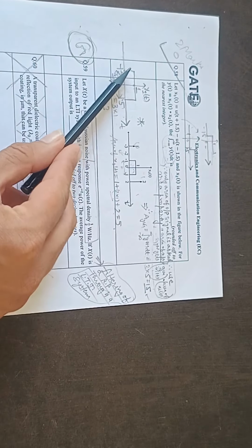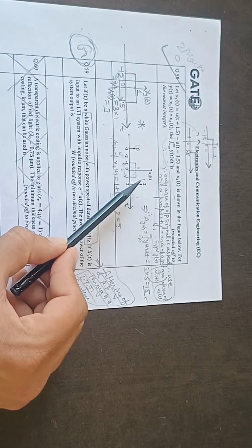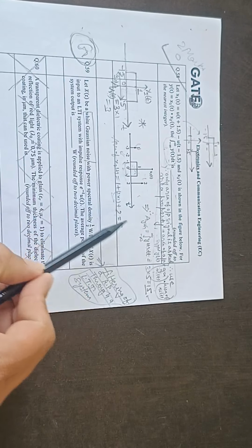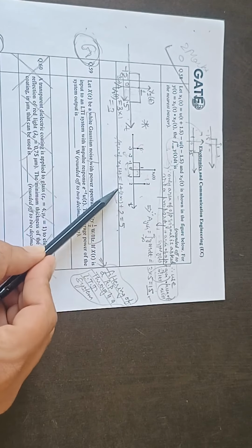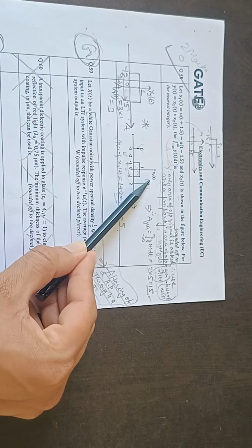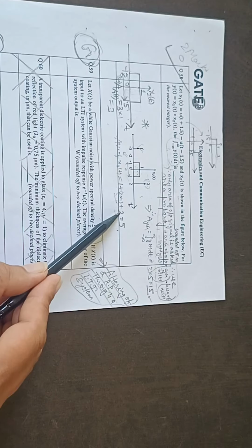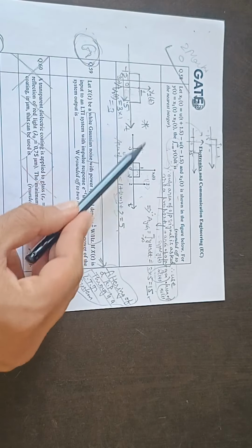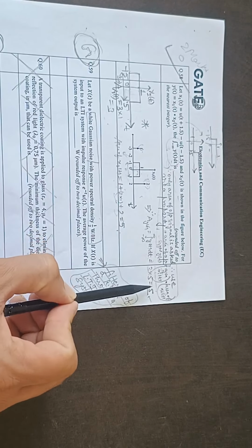This is a rectangle, so the area will be length into breadth, so 3 into 1, which is 3. The area of the other signal: this is a rectangle of width 2 and height 1, so 2, and this is an impulse, so the impulse has area 1, and this impulse has area 2. Note that this is not the height but the area of the impulse; this always shows the area under the impulse. So 2 plus 1 plus 2 is 5. The area of this signal is 3, this signal is 5, so when we convolve them, the area of the output signal will be 5 into 3, which is 15. So the correct answer is 15.